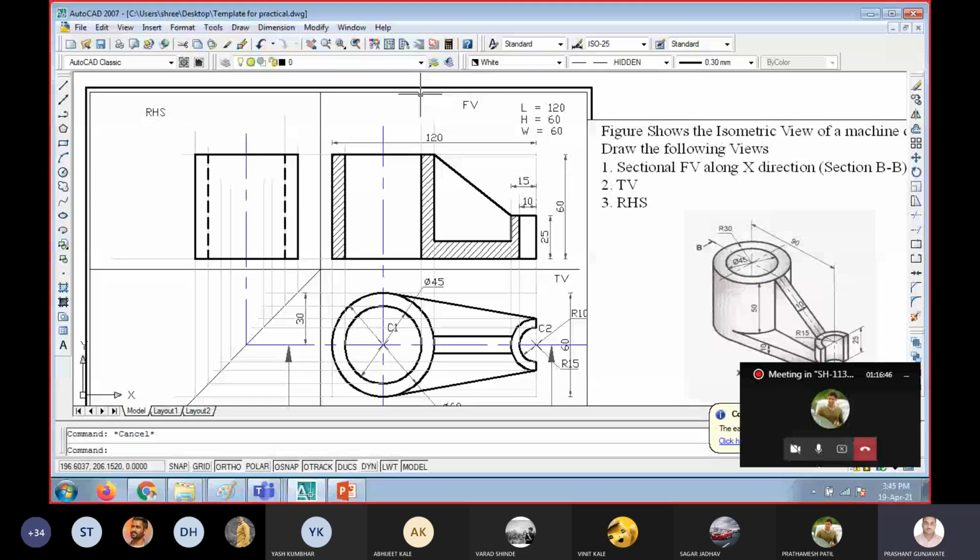Then here also we have drawn this cylindrical part with the outline, and there are hidden lines of the inner circle. Then let us draw the semicircular part. It will start from the base. It has a height, and you can take the height dimensions from the front view.